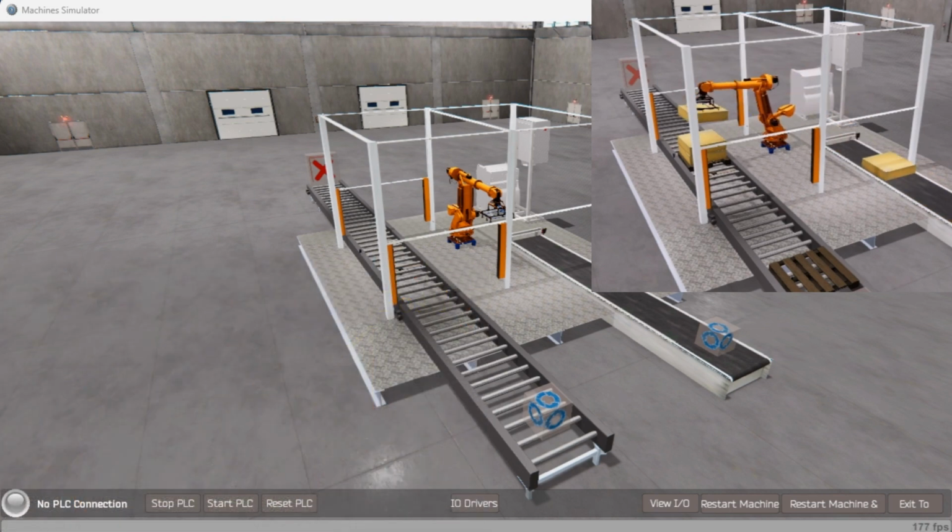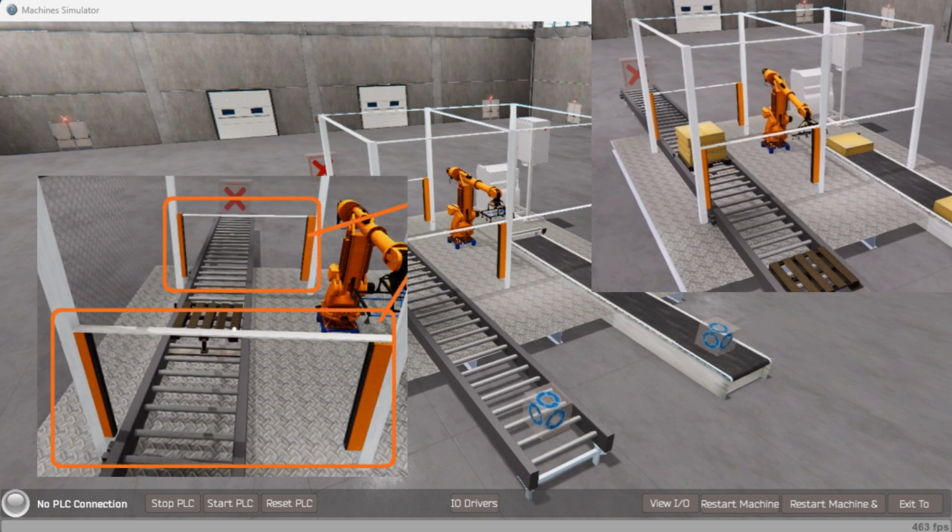The robot loader also has 2 light curtains. These are located on the entrance and exit of the pallet roller conveyor. If a light curtain is tripped while the robot is moving, this will stop all movement. A reset of the system will then need to take place to start the operation again.